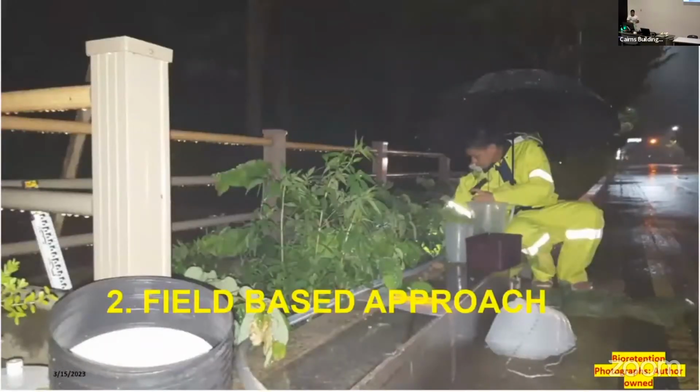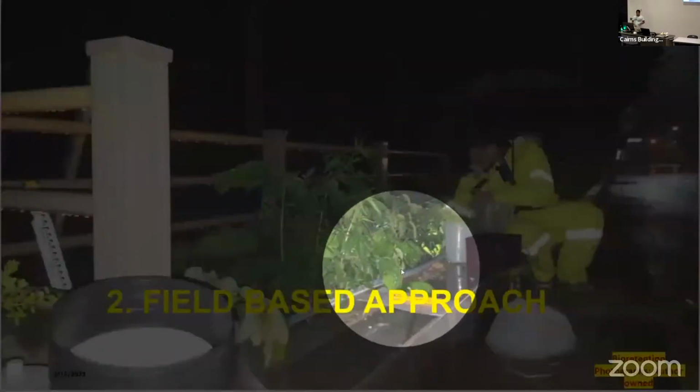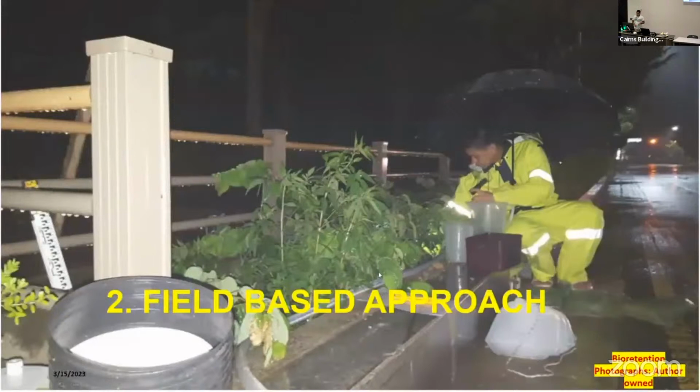So this is the introductory part of what the suite is actually trying to do in terms of stormwater management and flood mitigation. I have a few field-based slides from when I was involved during my master's research. This is a typical bioretention system installed in South Korea, where we replaced these inlets with a bioretention system. This system collects the runoff from the roadside and then infiltrates, retains, and detains it, going through different processes that help to mitigate the runoff.